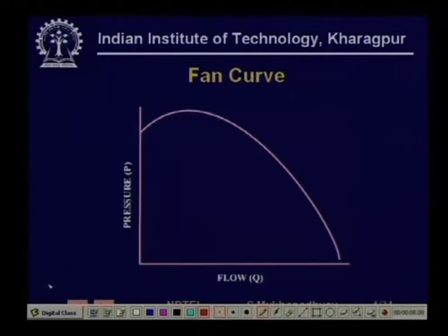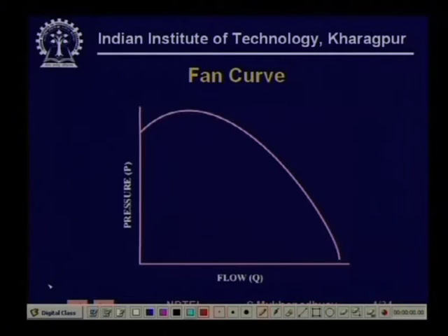Here, this is the intrinsic characteristic of the fan itself, irrespective of what the load is. So, the fan actually develops a pressure at its outlet and also develops a certain flow, and this it develops when the fan is rotated at a certain speed. So, when we have plotted this curve, whose one axis is flow and the other axis is pressure.